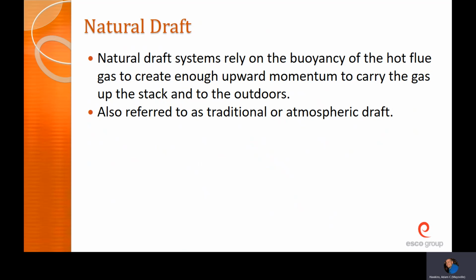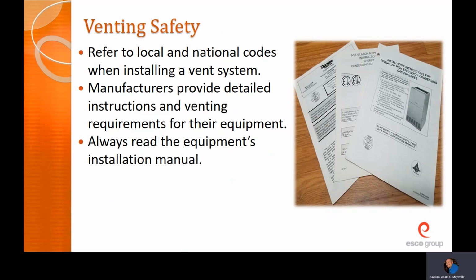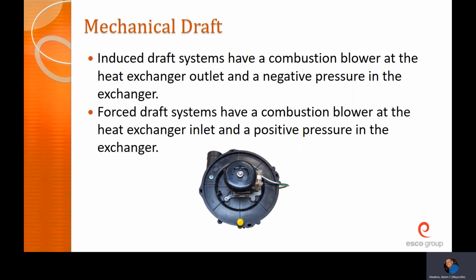It's obviously not as effective at getting rid of everything because you're not forcing it out, but it's the way it's been done for a long, long time. A lot of water heaters you'll still see use natural draft. So something else to consider: even if your furnace is forced, your water heater could be natural.